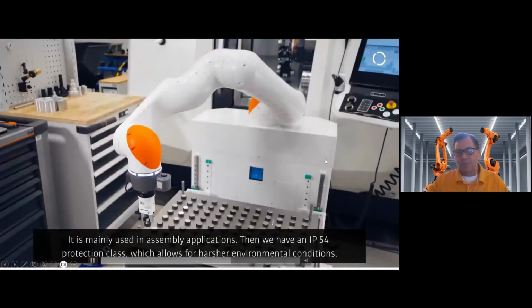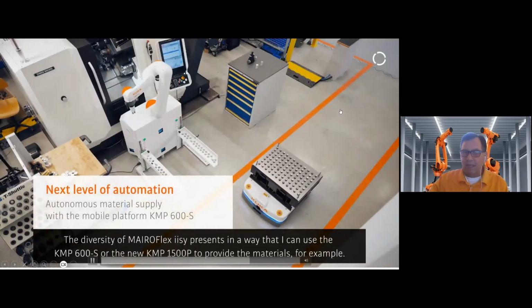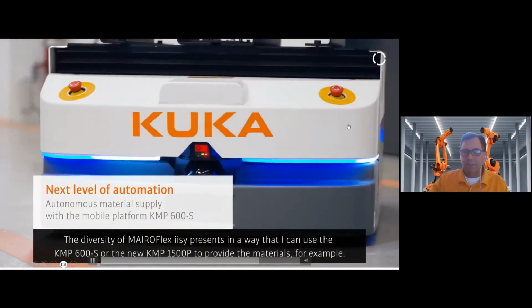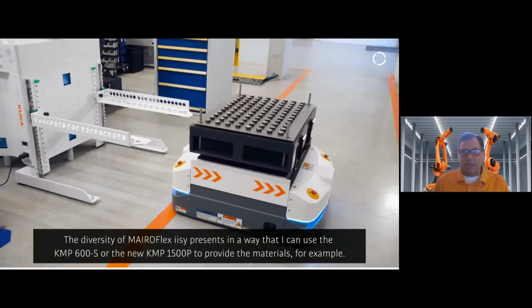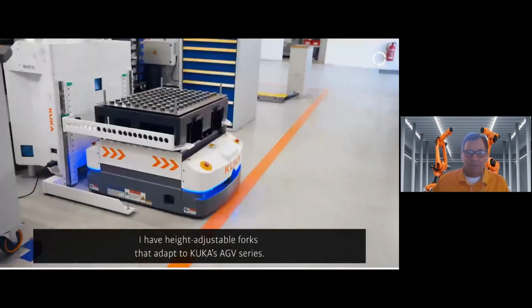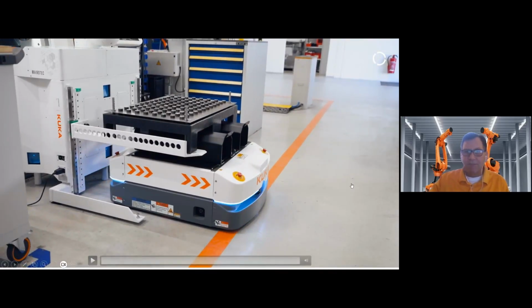This robot has protection where it has sensors to detect if someone comes into the envelope, and it would limit the torque on the arm if it happens to collide with somebody. You can see there was automation added with an AGV to load and unload the parts. And both of these pieces of automation have built-in sensors, so if somebody gets close, they're going to stop and protect the people.